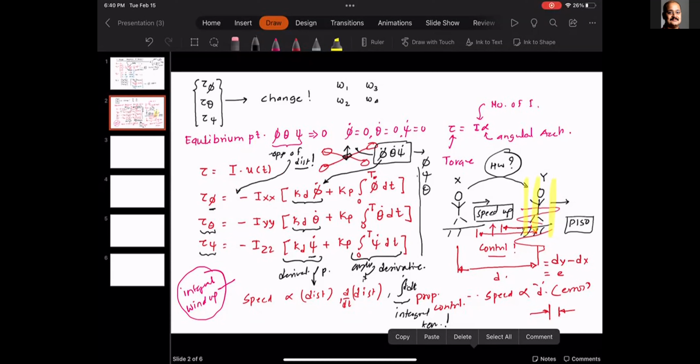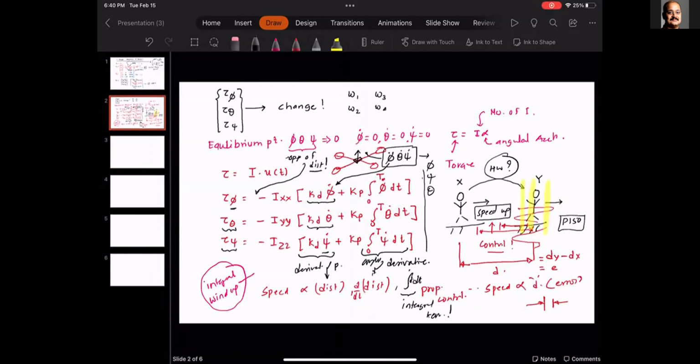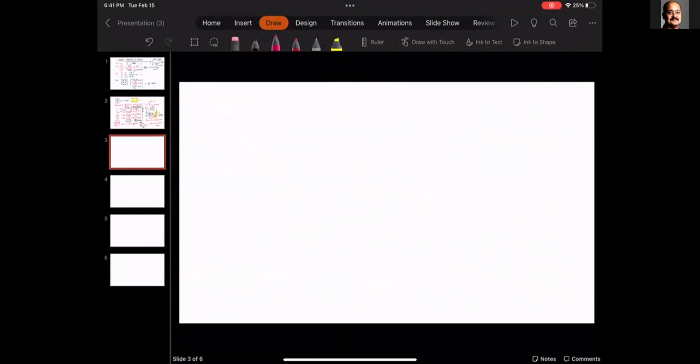So essentially, we want all the torque to be on that at 0, because we just have control over torque. The next part is, this is great, but how would we physically implement it? Please understand, quick recap: the only thing that is physical to our quadcopter are the rotor speeds. This is the only physical quantity. Everything else is derived from these variations in omegas. So I'm going to write the equation for torques.